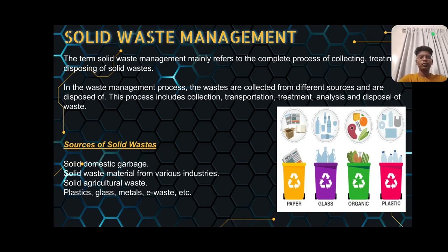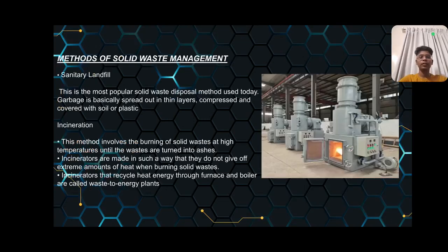There are some sources of solid waste such as solid domestic garbage, solid waste material from various industries, solid agriculture waste, e-waste, etc. Methods of solid waste management. Sanitary landfill. This is the most popular solid waste disposal method used today. Garbage is basically spread out in thin layers, compressed and covered with soil or plastic.